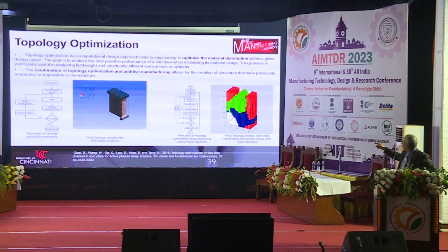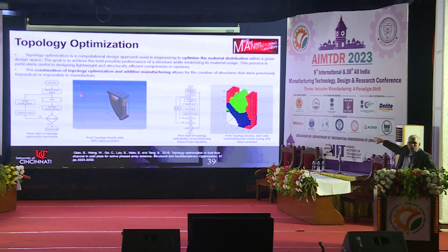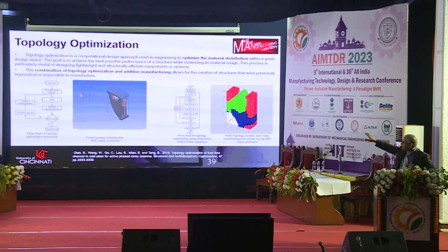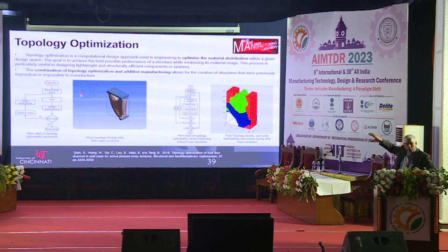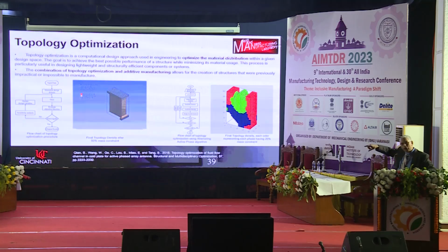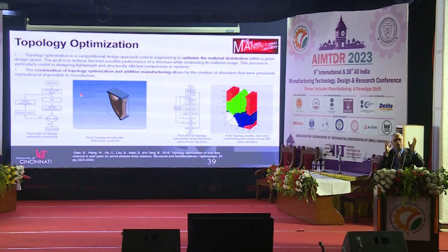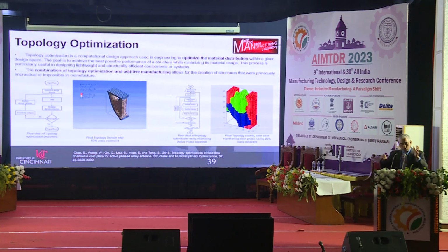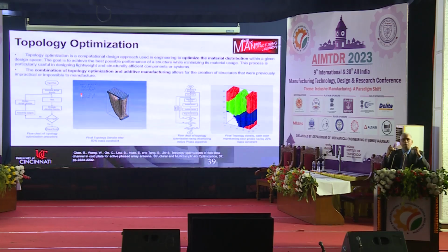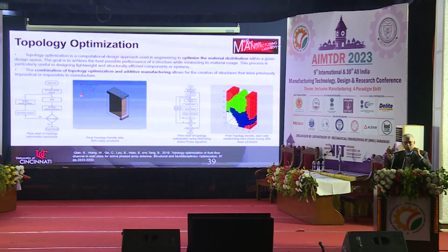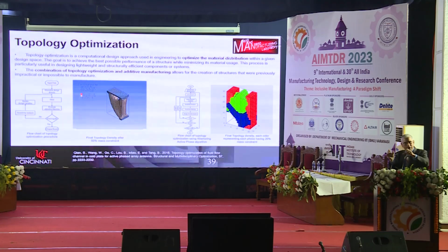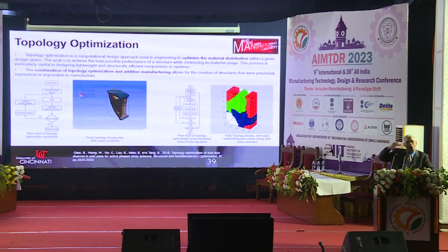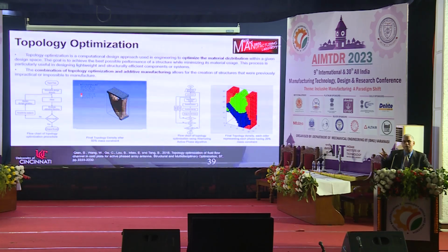What we did here, if you look at that flow chart, you will see two loops in it, right? The inner loop acts pretty much like the published work where you do the topology optimization. Then I put that into an outer loop. This time I try to replace material A with material B. I do this loop, and then I optimize the topology. Once it comes out as an optimized design, I introduce material C. So this keeps repeating. This way I should be able to do one step beyond the existing topology optimization.